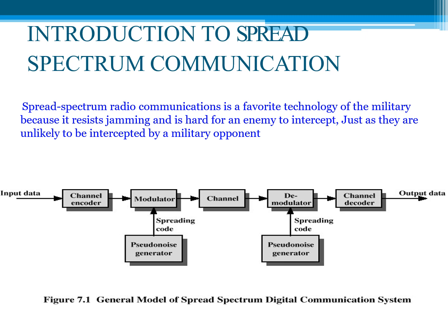At the receiver end, the demodulator gets the coded signal back from the spread spectrum signal. For this purpose, the demodulator requires the same pseudo-random sequence that was used at the transmitting end. Hence, the pseudo-random pattern generators at the transmitter and receiver sides operate in synchronization with each other.